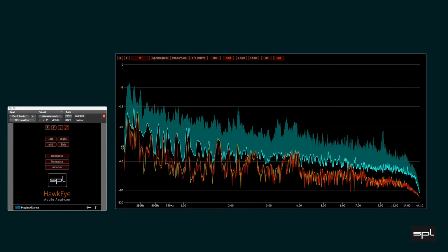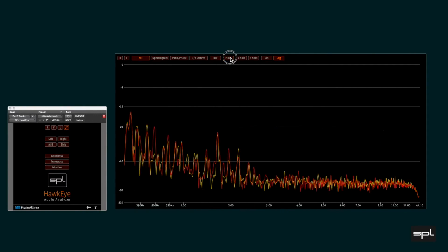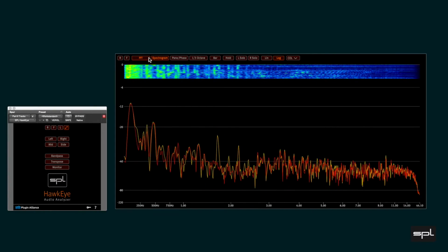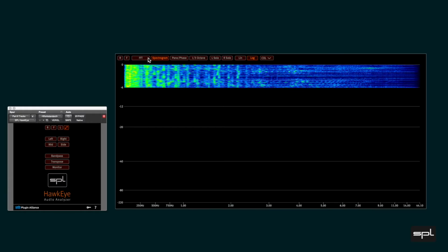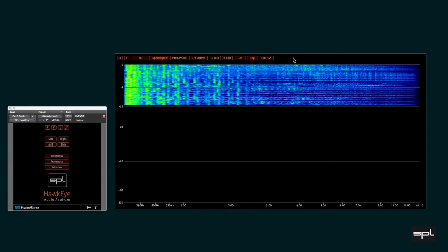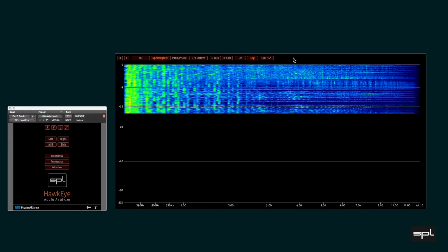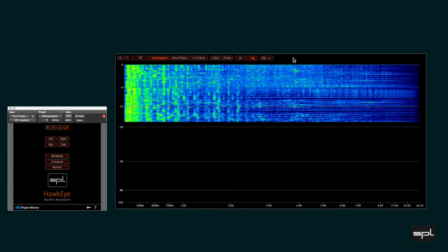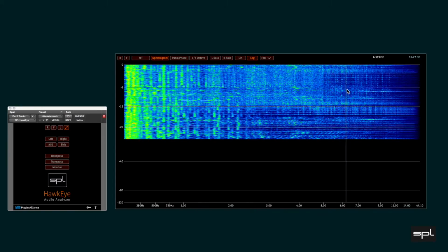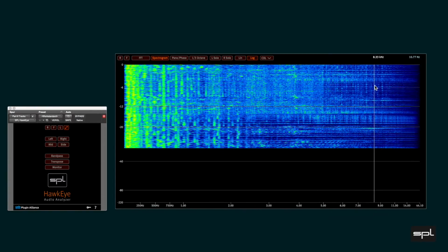The next instrument is the spectrogram, that shows a waterfall plot of the FFT. This tool detects periodic distortions in the audio spectrum that become visible as straight horizontal or vertical lines. Like in the FFT window, clicking into the window lets a vertical line appear and a precise frequency readout is given up here.